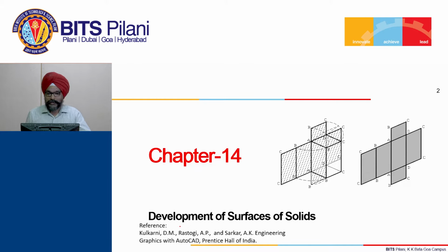By development, you can see typically, the solid which is a cuboid, the surfaces of that solid have been shown here. They have been put up on a single plane. Here you see a number of surfaces put up on a single plane. Here we have developed the lateral surfaces as well as the bases. Generally we do not develop the bases most of the time, only the lateral surfaces we develop. That is a practice, but if needed we can develop the bases as well.